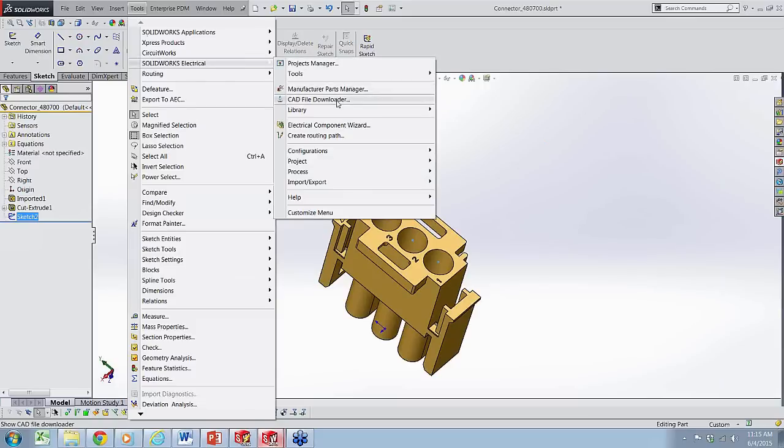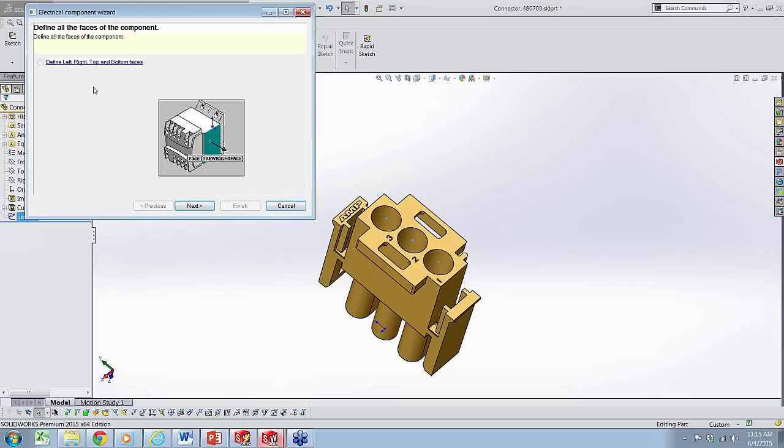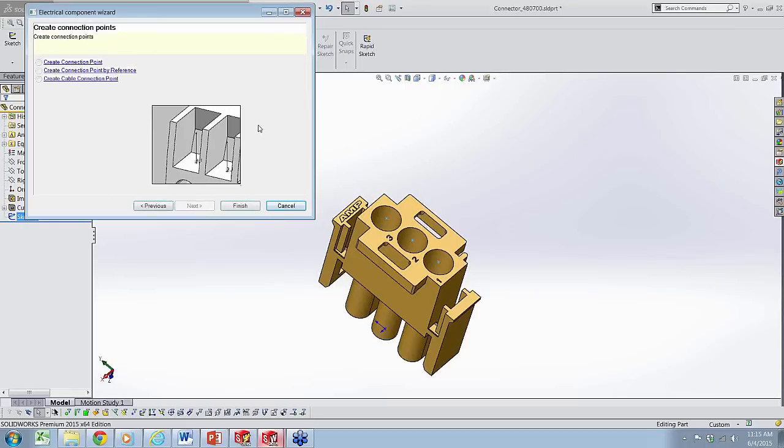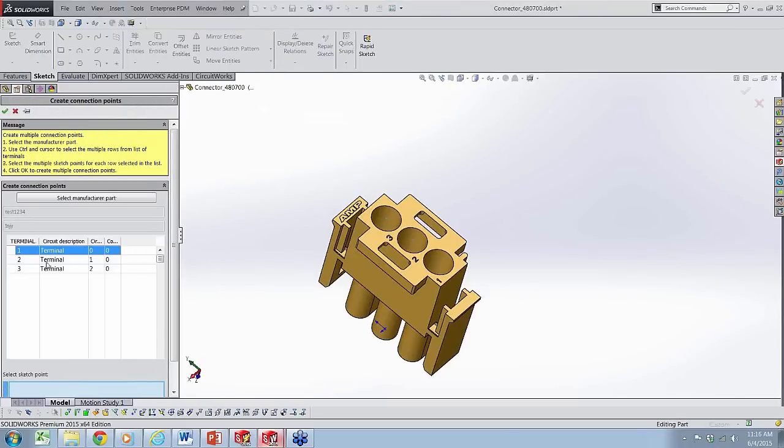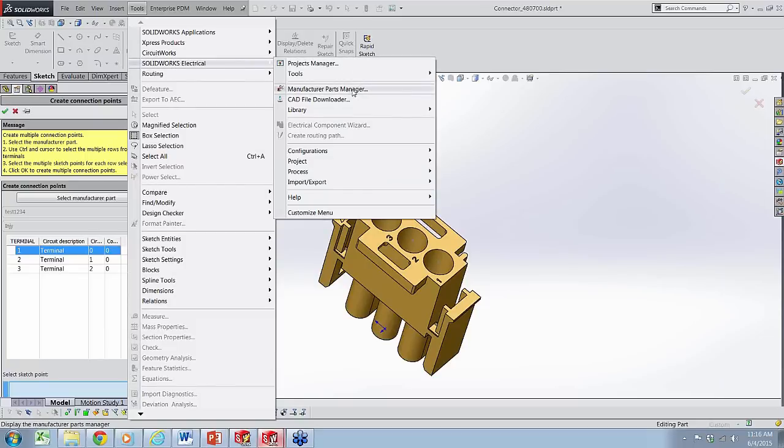What I'm doing in this step is not necessary, but it's going to make sense once I start defining the electrical component. So I put in 3 points, and then, as you see now, I'm going to go to the electrical component wizard. This is where it allows me to define the panel and rack mounted component, how you auto snap when they are brought into the 3D environment, and where all the wires will come off the component. So I'm going to choose by reference. And this is what I was talking about, because I made my symbol electrically intelligent when I created it, now I see all the terminal information. However, if that symbol has not been created yet in the electrical environment, I have access to the same manager through the schematic, through the mechanical space.